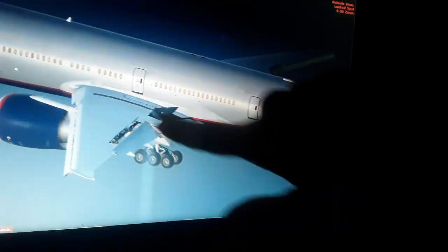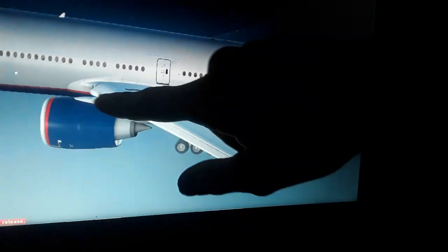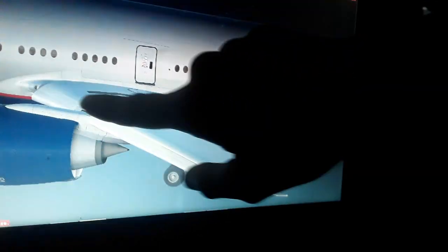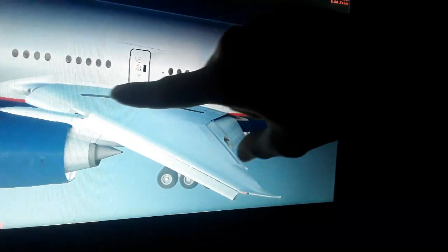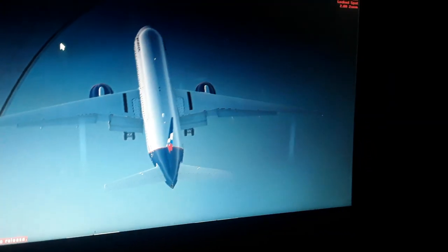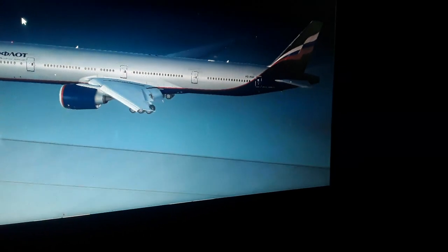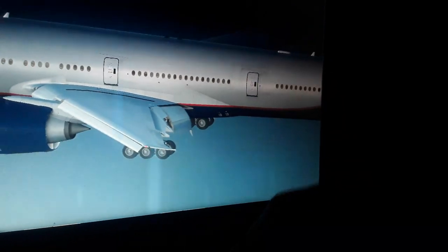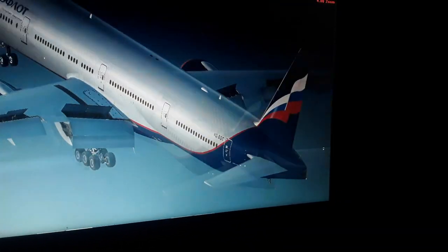Also, the top surface of the wings, you can see, is more curved. It has higher curvature. So using Bernoulli's theory of fluids again, the airflow moves much faster above the wing, so the air has lower pressure. It has negative pressure above the wing. So this creates a suction above the wing. It sucks the aircraft weight up into the air. So we have the differential pressure upward: lower airspeed below the wing with higher air pressure, and lower air pressure above the wing with higher airspeed. So this is the explanation.